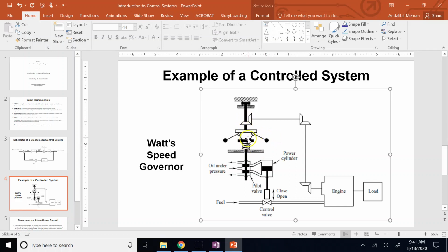It wasn't exactly like that. This object was connected to a spring that was preloaded, and that shaft was connected to the hydraulic valve, and the hydraulic valve was controlling the position of the inlet valve. So what happens really is, as these two guys extend, not only does this RPM change, the vertical position of this object, which can freely slide up and down here, this black plate, can change accordingly.